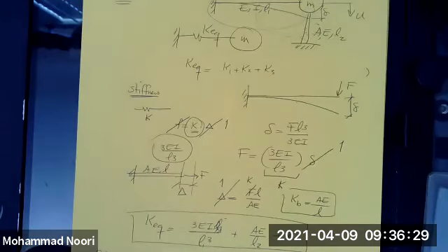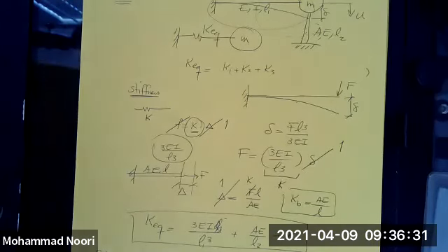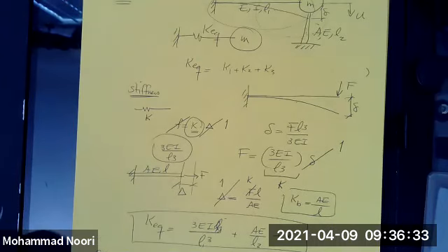Yeah, Professor, I have a question. Sure. Just to clarify, if they're subject to the same force, it would be series, and if they have the same deformation, it would be parallel. Exactly. That's what I want you to remember, and not fall into the trap of this business of series and parallel. Same force.